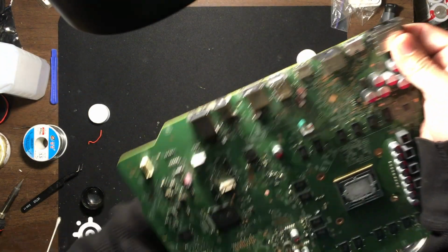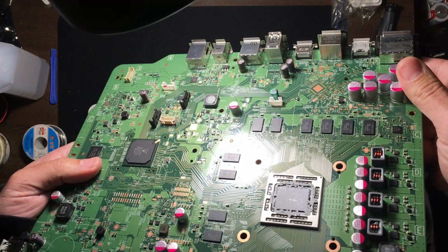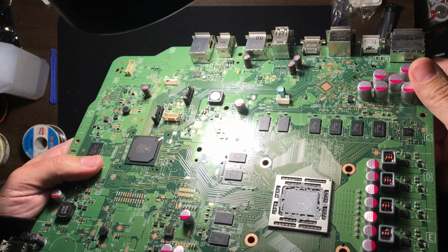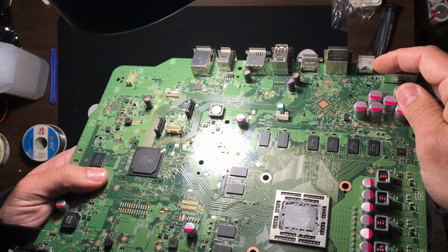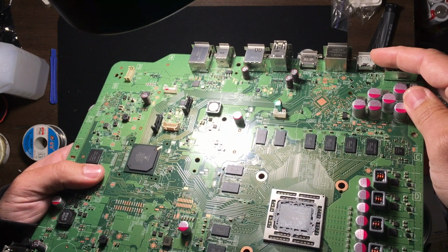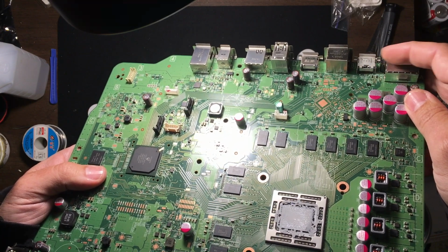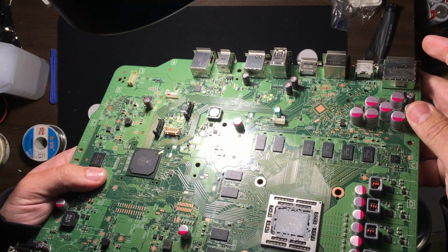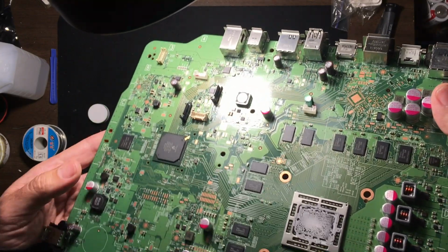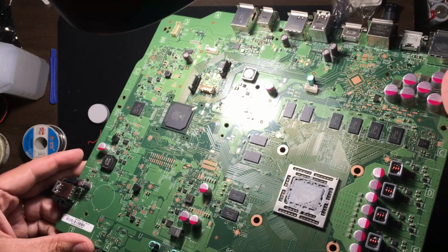And then with a magnifying glass, we have to go through and check that they're all pushed down, and we're going to apply a little bit of heat across all these pins here. I'm not going to add any solder, because if I add solder, it's likely that I will start bridging connections, and with how tiny they are, it's going to be a real pain. So at this point, I want a pretty clean soldering iron, and just run it across the bottom there.